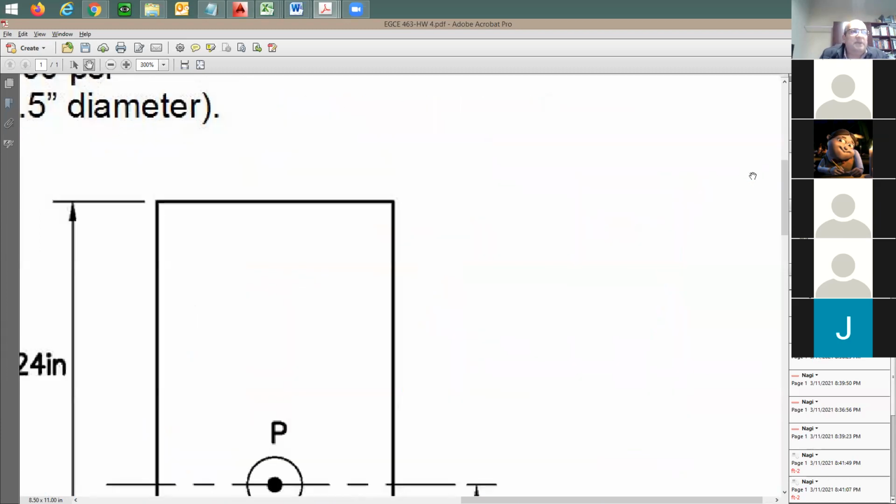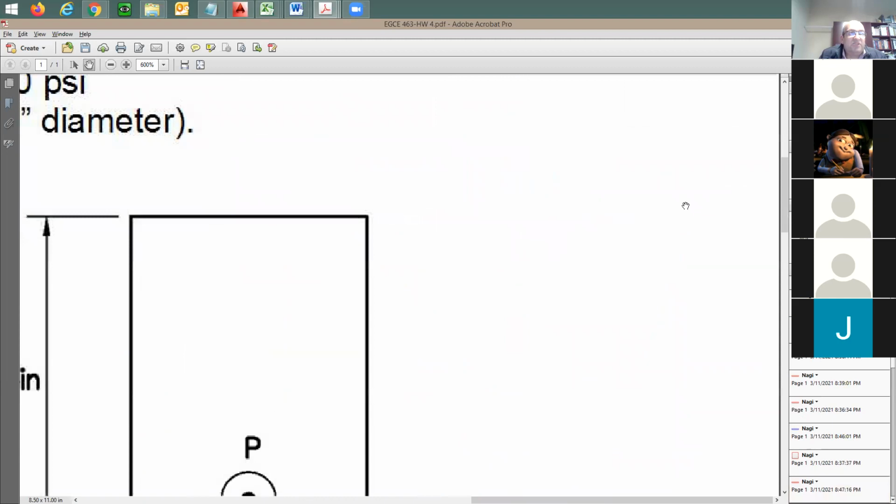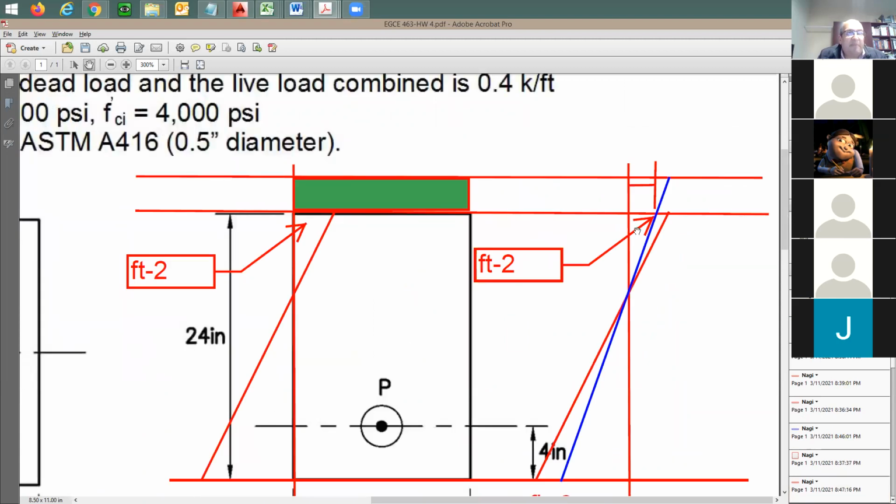If I may zoom in here, this new value is from this point to that point, right? This new value from here to there, which means the stress at the top of the beam itself needs to be added to the stress which was right there, which was this one, right? In stage number 2.